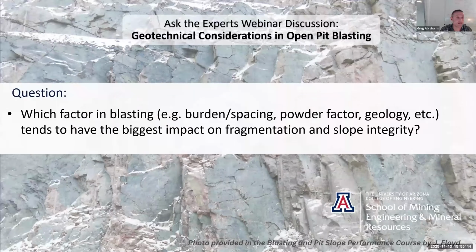And then, I suppose the last part of slope integrity is if we're mining below or close to an instability, then there's the vibration piece. Perhaps we're talking more about getting into the far field there. And that's where our frequency control, timing can come into play, the value of doing signature holes, understanding the PPVs and developing a site law and so on.